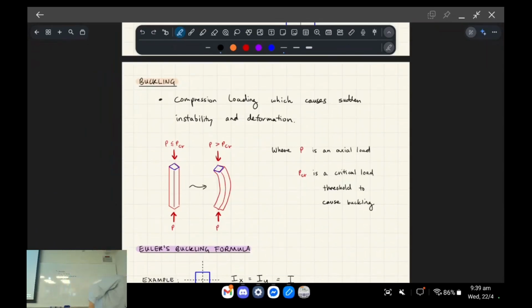So I've actually got some balsa wood for a demonstration, right? So, okay, I've got 2 pieces of wood. I've got one that's a rectangular cross section with pretty extreme differences between the dimensions, right? And then I've got one which is a square, okay? So just on the one that's a square, if I compress it, I'll do it so that the video can see it, it will just buckle, okay?